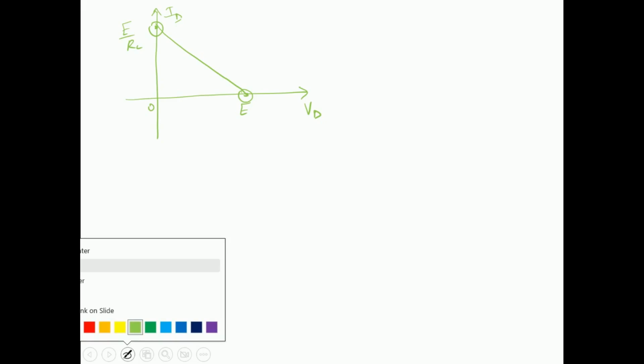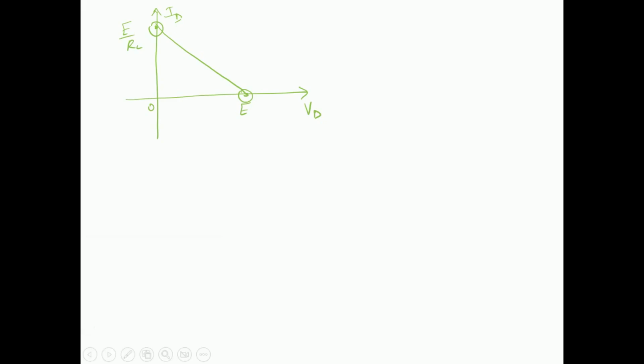For example, this is the load line which we got. So let's say this is our load line. This was the maximum voltage. So this is voltage Vd, this is maximum Id, this is 0. So the values of maximum current and voltage come out to be these points, and the slope is basically a falling slope over here. So we can verify that the load line we have just drawn follows a decreasing slope, and we can mathematically prove it.